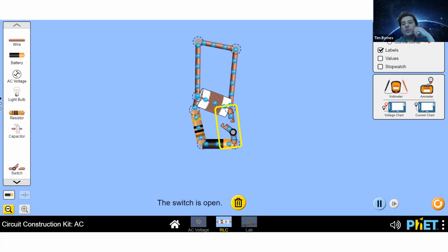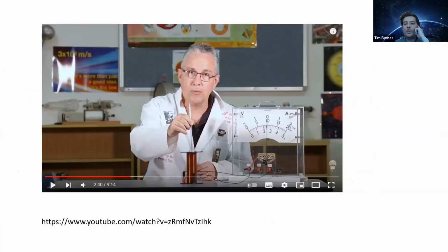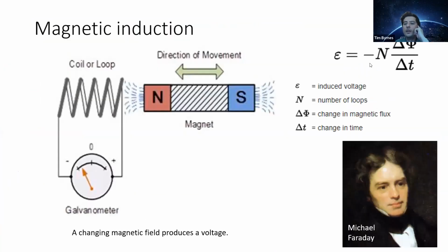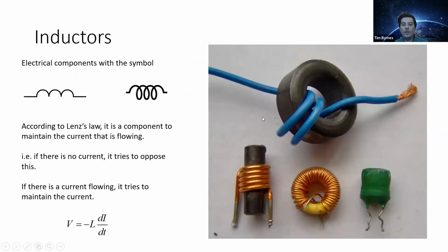This whole effect comes from the fact that inductors take advantage of this property that it just does not like the magnetic field to change. And the reason why in the inductor formula over here, it's not magnetic field but current, is because the current and the magnetic field are related things, right? So if you have a certain amount of current, then a certain magnetic field would be inside here.